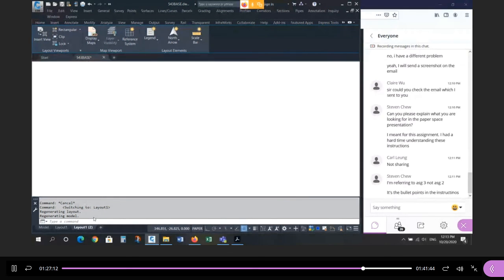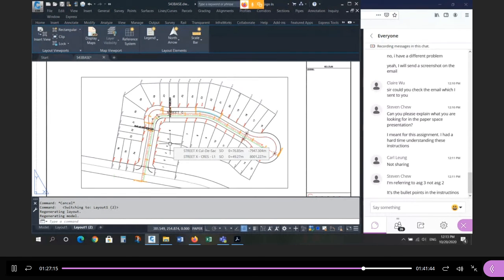When you do a grading plan, it represents what's on the surface of the ground. So you shouldn't see anything underground. So no pipes. Maintenance holes, yes, but no pipes. And so on. I'm going to talk more about that as we get closer to the end. Okay, I'm not going to be too picky, but certainly some things you never want to see.